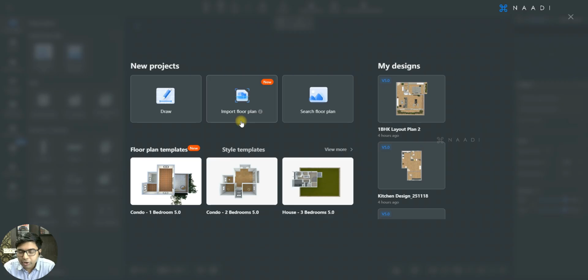Generally, before starting with your interior modeling, we'll first try to model your floor, wall, ceiling. We'll try to create your door opening, window opening. We'll try to place your doors and windows, right? This is what we call the basic model. And once your basic modeling is done, you'll take your furniture models and place them in your project. Then you'll create your wall panel, false ceiling, play with finishes. You will create your lightings appropriately, and together you'll complete your interior modeling. This phase is what we call interior modeling.